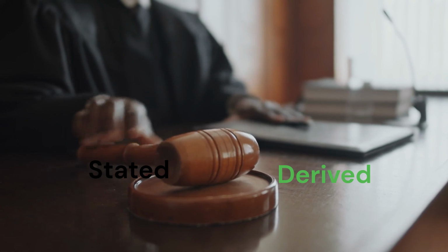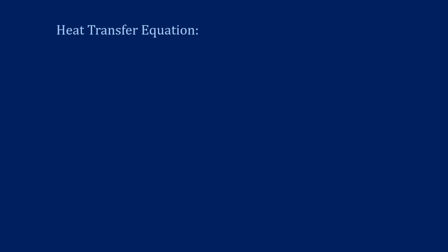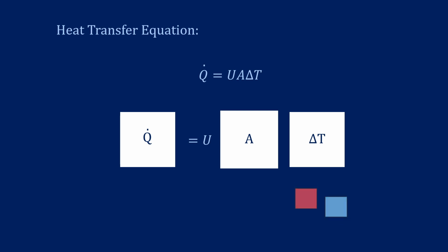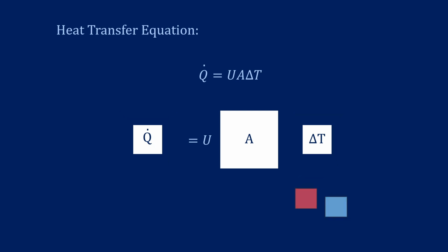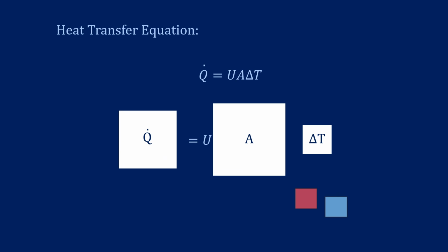This is really where it becomes an engineering problem. If you want to reduce entropy generation to make your system more efficient, you need Th and Tc to be as close as possible, minimizing that temperature difference. But now, let's take a look at the heat transfer equation. Q dot equals U A delta T. If delta T becomes very small, then to maintain the same heat transfer rate, the required surface area A must become extremely large. Visualize this.